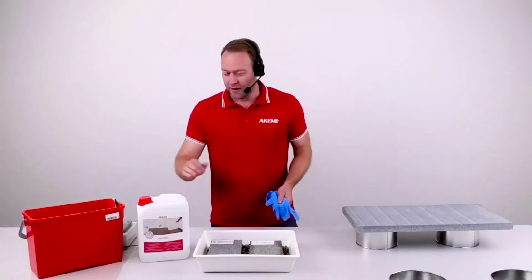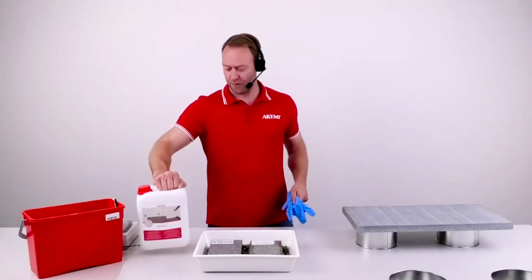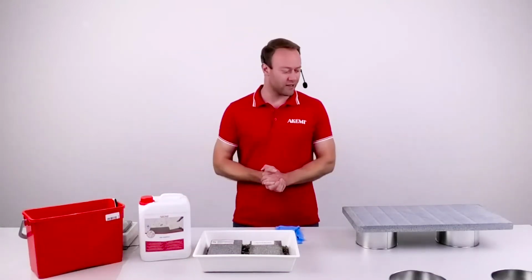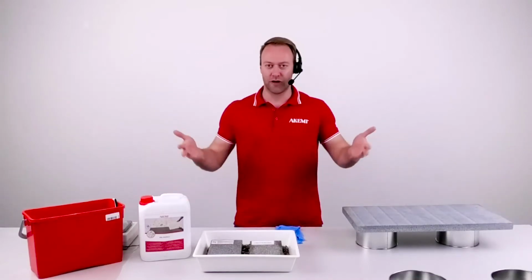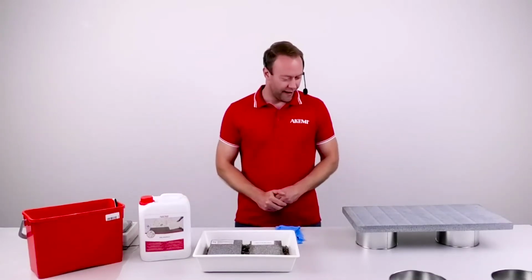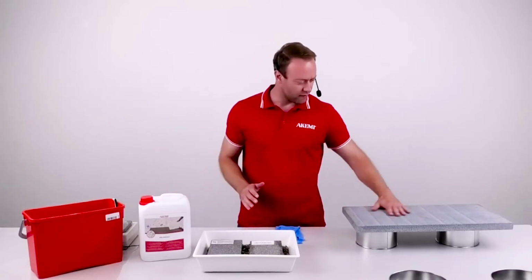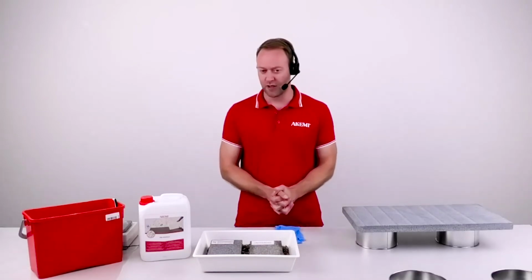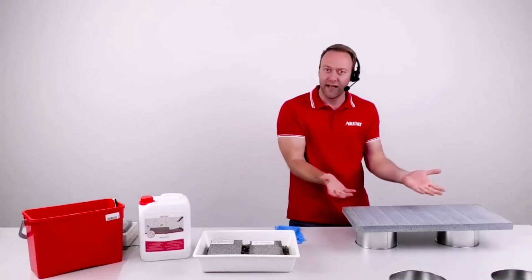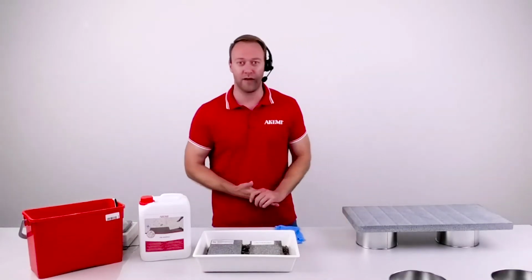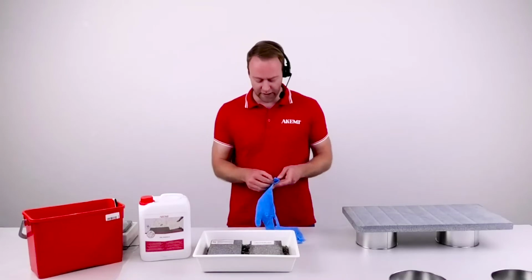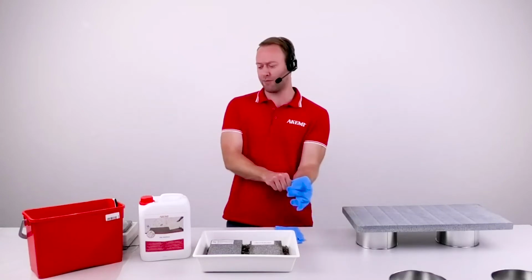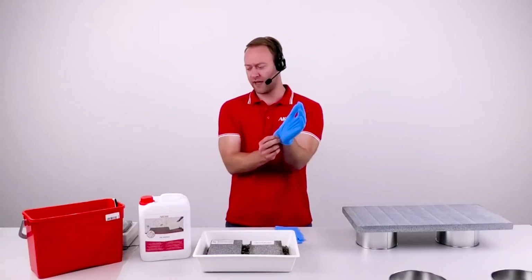So this is Pre-Protect, 5 liter. We only sell it in 5 liter, not in smaller sizes, because usually you use it on terraces. We have at least, let's say 30, 40, 50 square meters, I believe. On rough stones, you can cover, I don't know, 10, 15 square meters with 1 liter. Then both sides maybe, so it's like 7.5 square meters for 1 liter. Then a 5 liter canister is good to use for 1 terrace. I use gloves because the product is quite alkaline. So better use gloves when you use it.